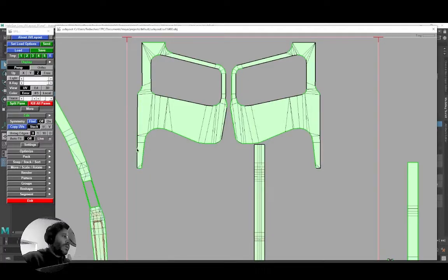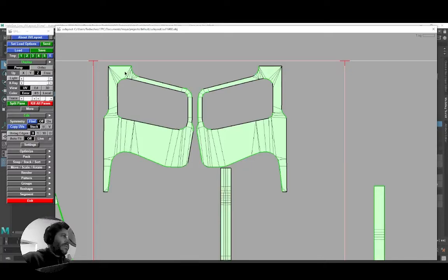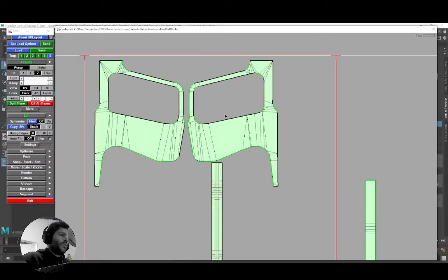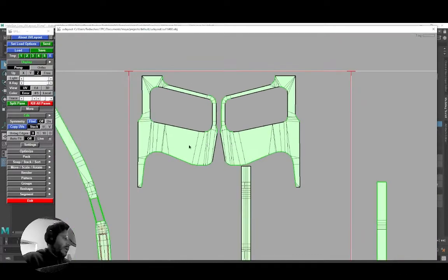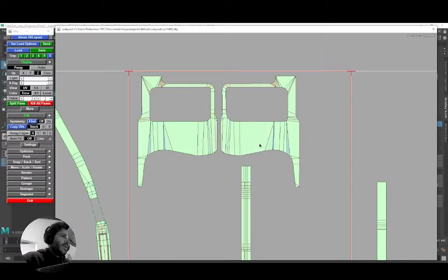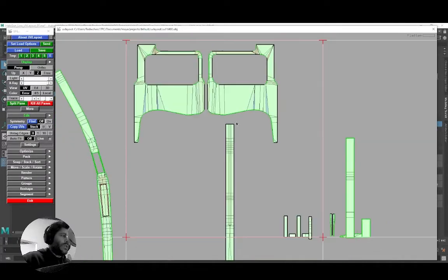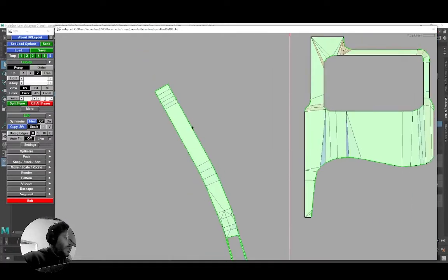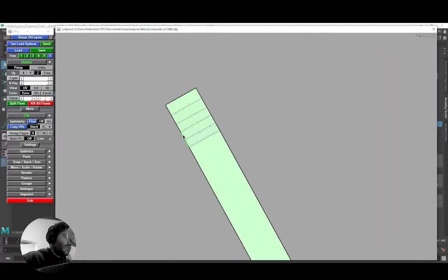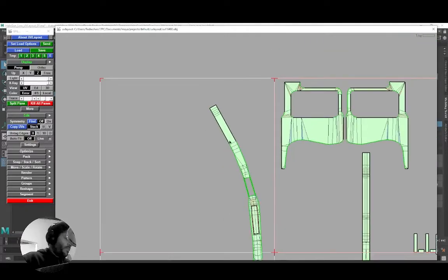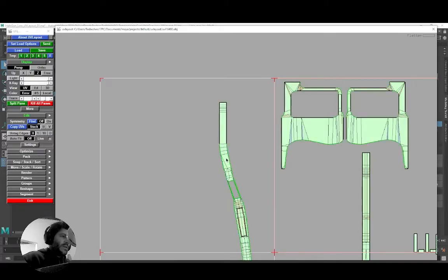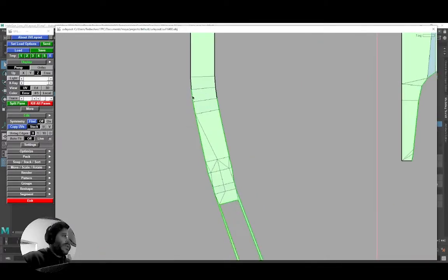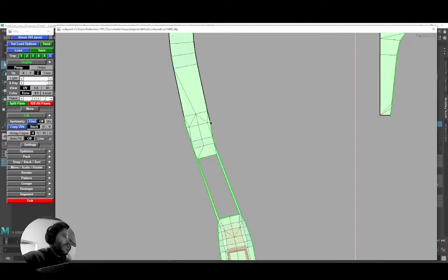So there we go. Maybe like so, and maybe we can remove this one with Shift I. You can remove which edges you want to rectify, and now maybe I want to rectify also this one, and now press F, and you will rectify only those edges. In this case, we're going to do the same. I. So we can rectify all these edges. Also, you can do this and press F, and then continue rectifying the rest of the UV island.